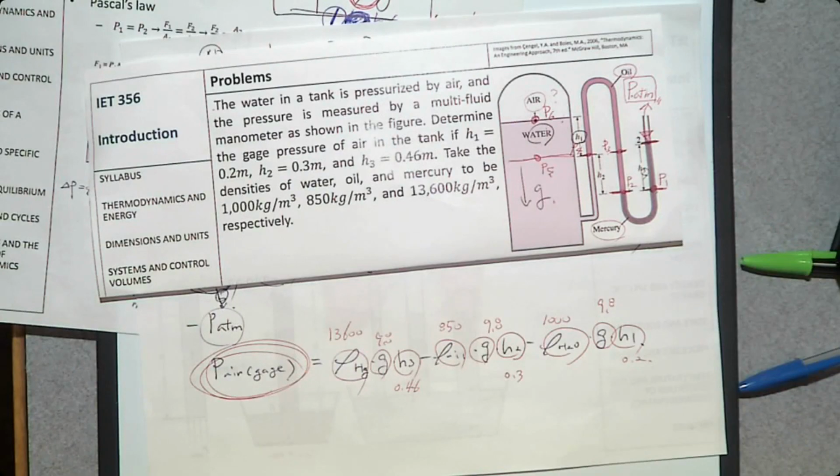You only have two options, either going upward or downward in the same tube using delta P equals rho g h. If there are no more points you can move up and down, then you find another location, an imaginary surface, that is connected in the same fluid at the same elevation. If you cannot move in both ways, that means you went too far. Go back and find another location.